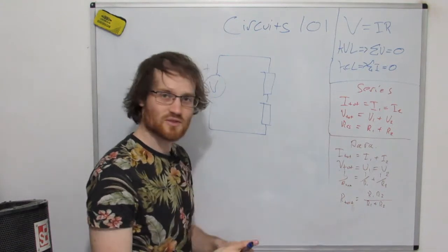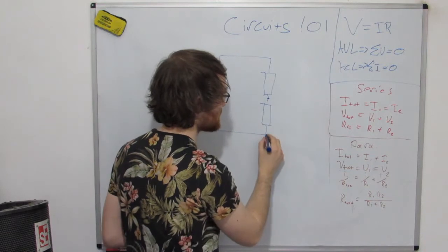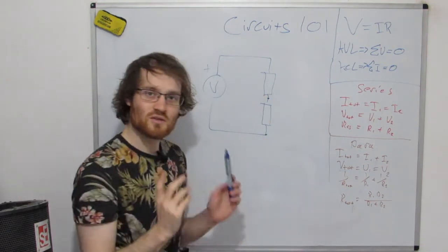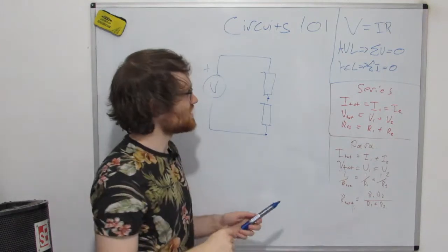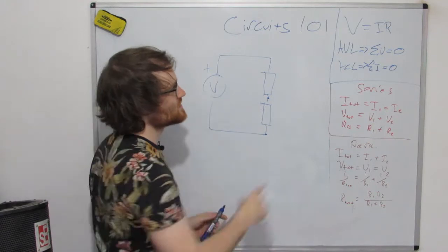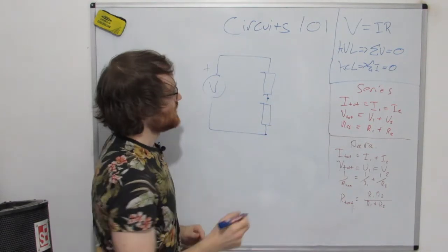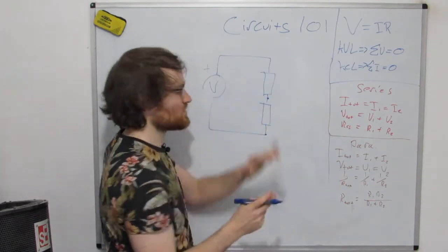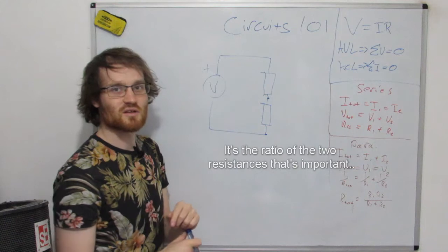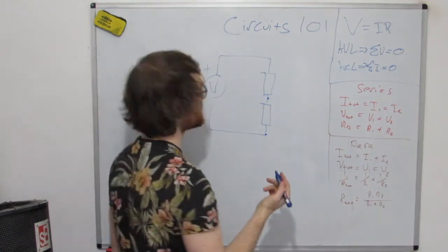And as we said, we saw this before, we can calculate the voltage drop across either resistor by knowing the ratio between the 2 resistors. That is going to be the same ratio, because they've got the same current, V equals IR. So if you change the resistance, the current doesn't change, so the voltage has to change. So it doesn't matter what the values of the resistors are, only you want to be careful not to draw too much current, because they can only take so much. Your power supply can probably only deliver so much.